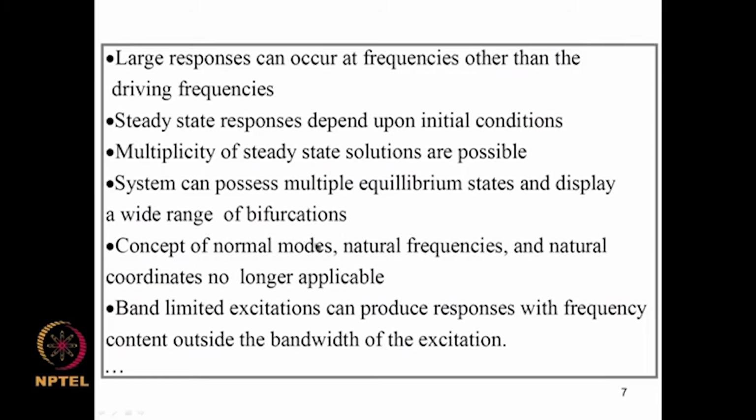Then the concept of normal modes, natural frequencies and natural coordinates are no longer applicable for nonlinear systems. So, you cannot uncouple the equations of motion through a transformation. Then band limited excitation can produce responses with frequency content outside the bandwidth of excitation. So, this again is a very important aspect of nonlinear system behavior, both in response analysis as well as in experimental work.